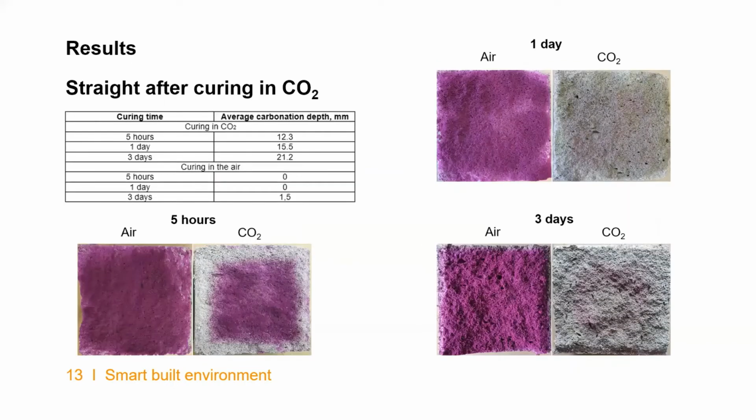So, results. These images show samples taken straight out of the curing chamber, split and sprayed with phenolphthalein, which shows how much of the cross section is carbonated. The purple area is non-carbonated, and the clear area, where you can just see concrete, is carbonated. When the samples were in the curing chamber for 5 hours, the carbonation depth was 12 millimeters, and for the sample left in the air for 5 hours, the carbonation was 0.